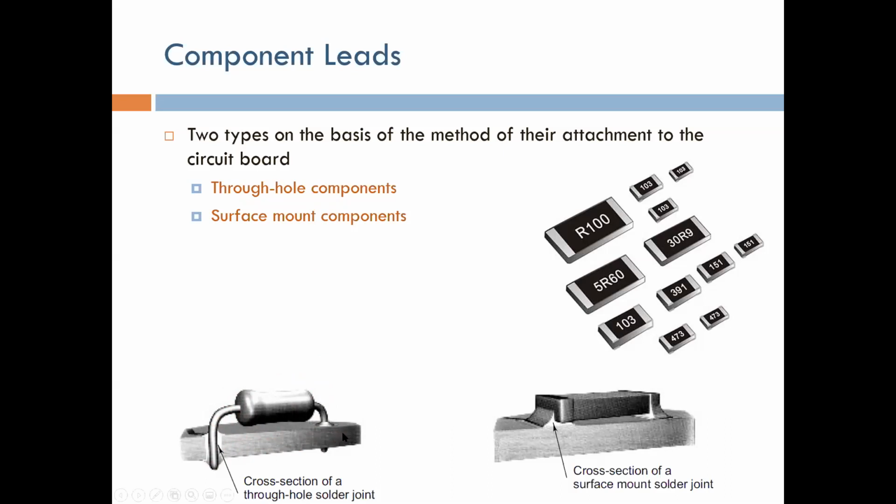The problem with that is, for modern printed circuit boards, for example in a computer, you have so many connections, so many tracks that you have to use to connect components to each other. It's very difficult to use a board that has holes because it's difficult to connect very high density components when you have holes going from one side all the way to the other. Also, we now have multi-layer boards, which usually have tracks running below the components, so that you can resolve overlapping tracks. So these are very inconvenient. Through-hole components are usually used for either a very old circuit, a very simple circuit, or if you want to do prototyping on a breadboard.